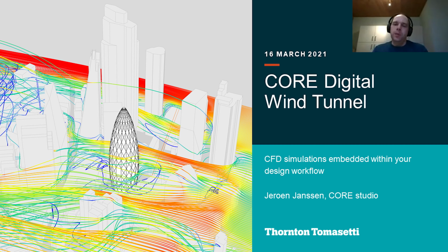Yes, so typically what you would do is at the end of a project, when you go to a mock-up stage of the facade, you would put a one-to-one mock-up in the facade, and you look at things like loading on these individual brise-soleils. I'm also thinking about whistling sounds, the aeroelastic and acoustic properties of these brise-soleils.